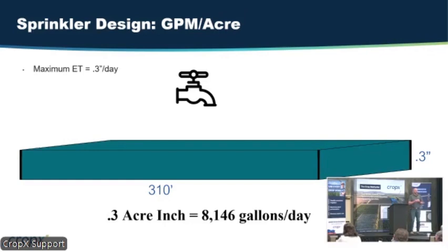So I've heard a lot of talk about NRCS agencies and all the different things that come about with those guys. The hard part with NRCS agencies, you know, they set federal minimum standards, then state level, then local level, right? Some local levels will say you have to have a soil moisture probe for every 40 acres irrigated. Some will say 1 per pivot. Some will say you have to maintain at least so many GPM per acre on design. Okay, so what they're talking about is we know in this part of the world that your maximum ET is this, so we know you have to have this many GPM per acre to catch up.